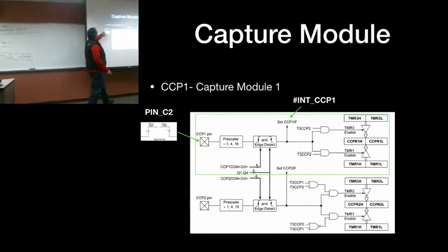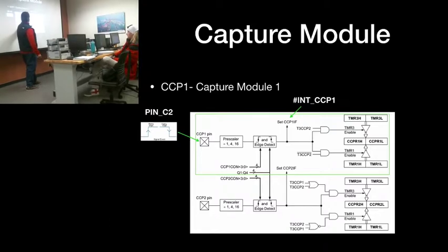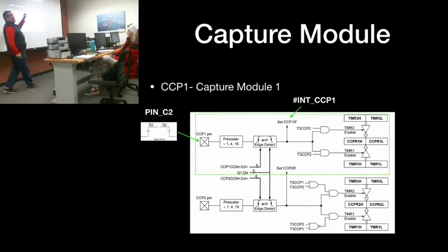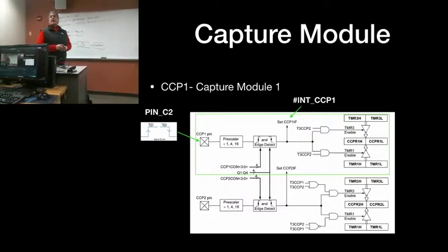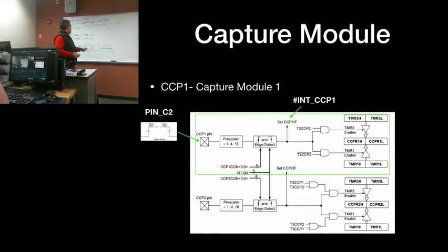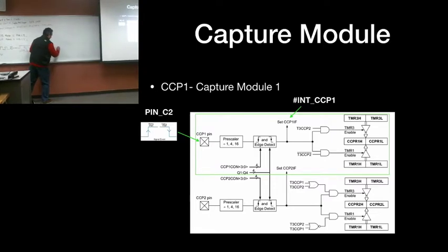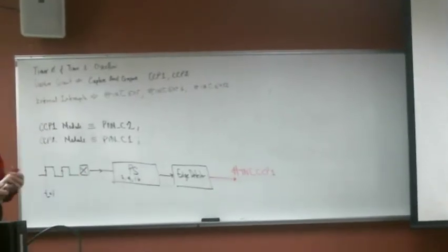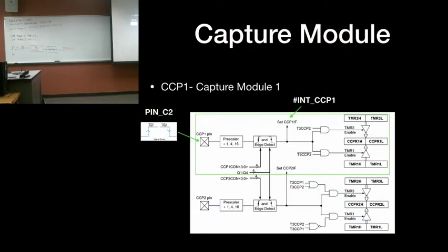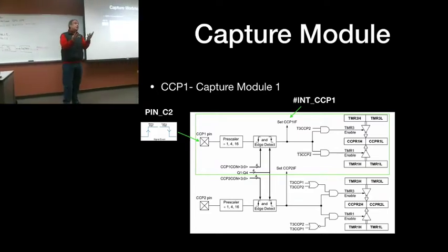And so what's going to happen is that after I send my event, whatever that event is, the device will detect it and an interrupt gets driven. Now, the pound int underscore CCP1 is the interrupt that our compiler understands as the triggering event. So this guy will trigger this guy, if properly configured, of course. All right? Now the question is, what is that interrupt doing? In the previous circuit, you press a button, the machine goes, I saw that. And now you decide what to do.